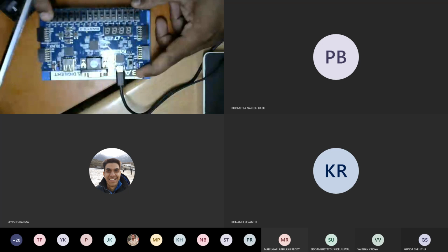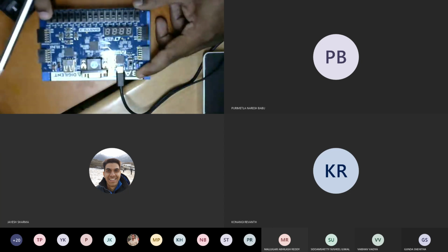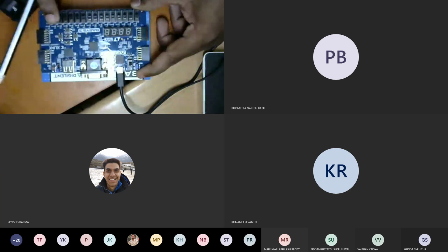In a lab, most of the time you want to apply logic 1 and logic 0. So for your full adder, for instance, you can map your A, B, C to these 3 switches and really apply different combinations, from all zeros to all ones, just by changing the switch positions.